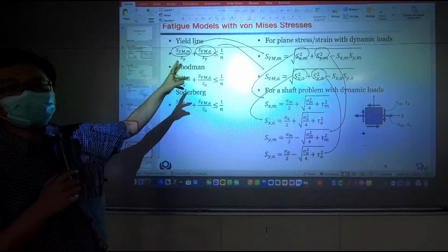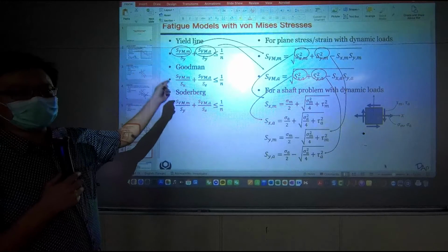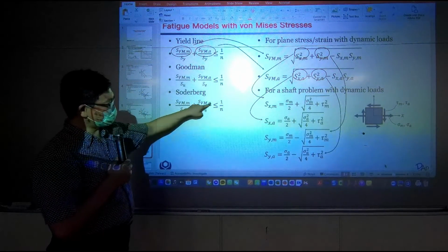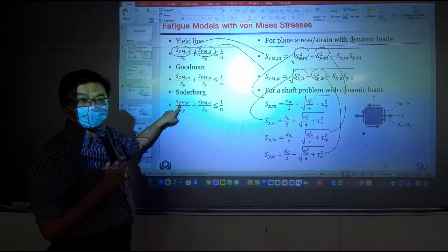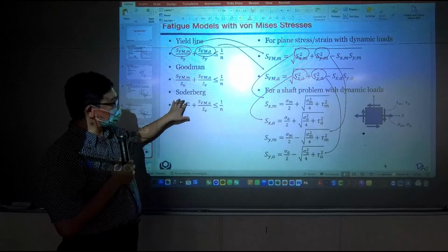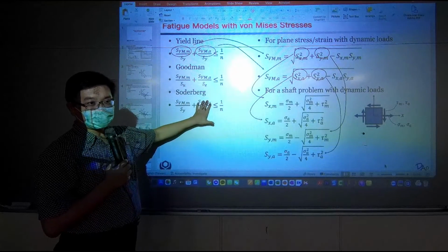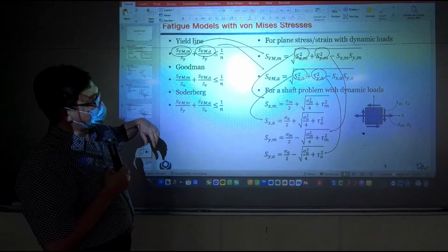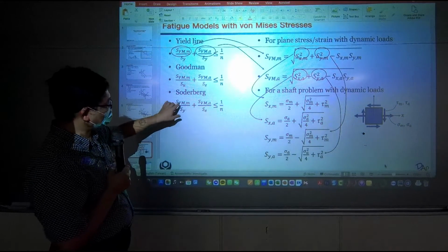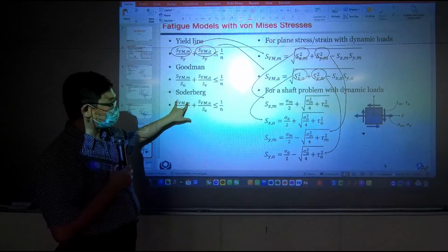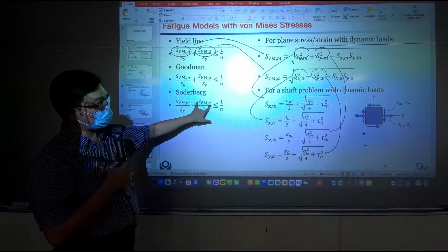So, if we can apply von Mises stress to our fatigue model, at the upper parts, they are all von Mises stresses, including the average ones and also the amplitude ones. And we can then try to figure out what would be the mean of the von Mises stress and the amplitude of the von Mises stress.